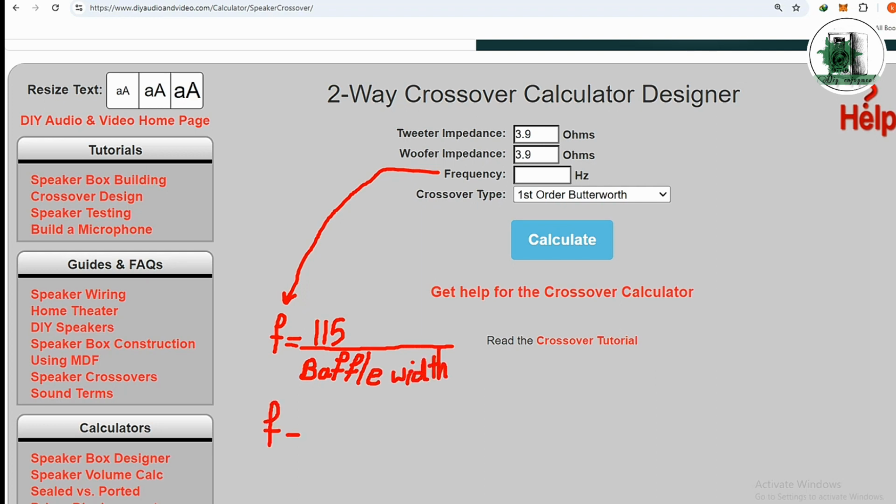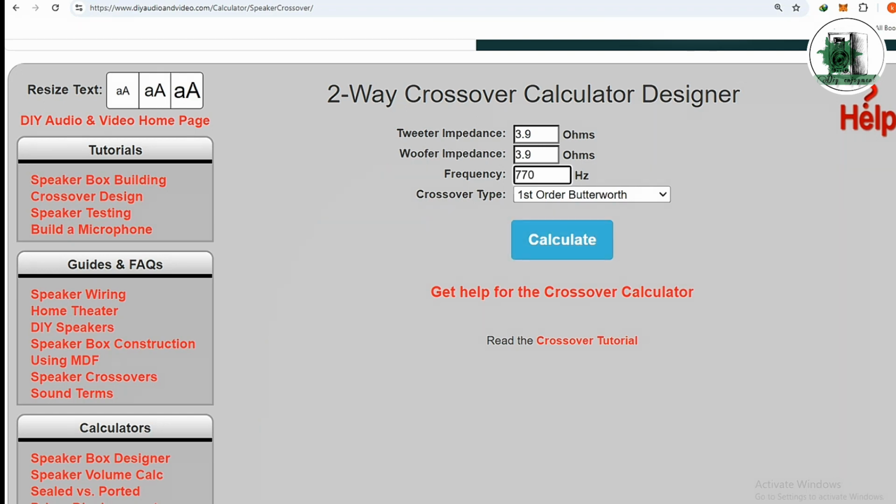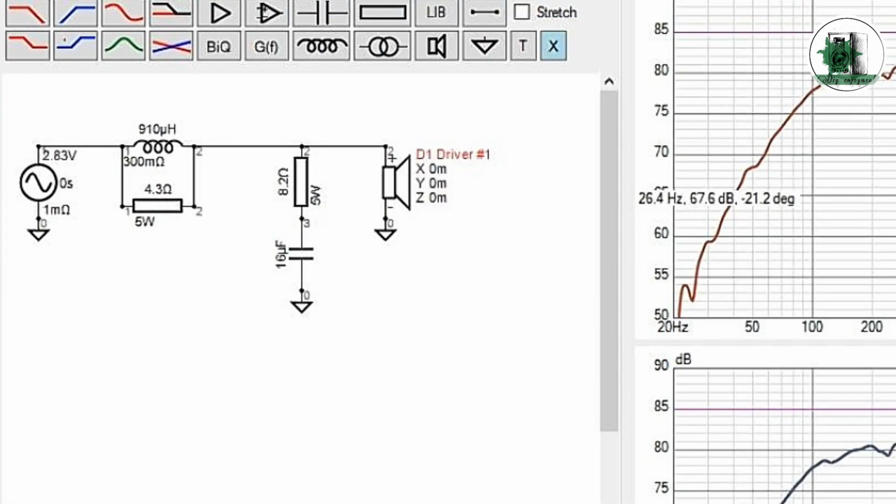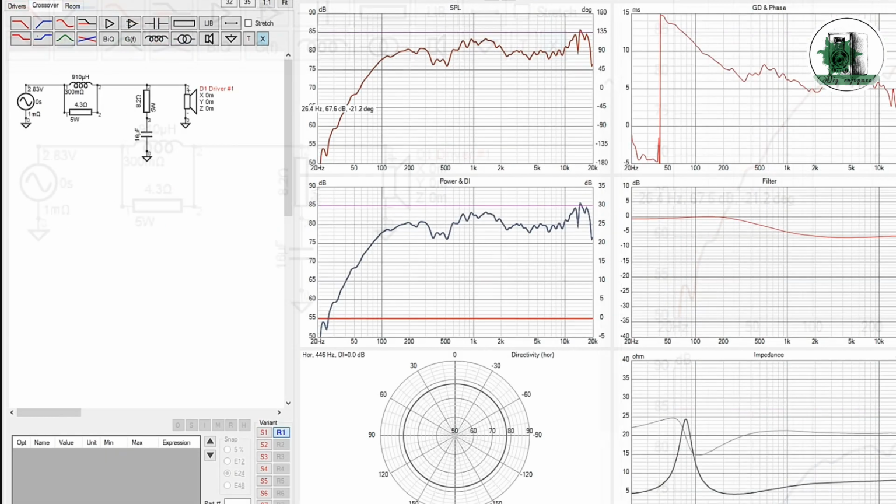We determined the width of the baffle in the diffraction tool to be 0.15 meters. Since we need to reduce the high frequencies, the low-pass filter, including an inductor, is enough. I select a higher value for the inductor. You can try some values close to the calculated numbers. The parallel resistor adjusts the level of the high frequencies to be equal to the lows.